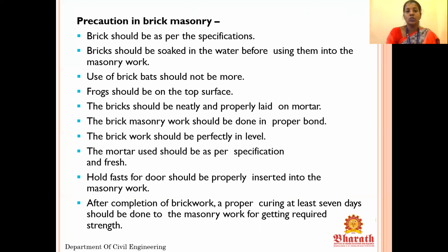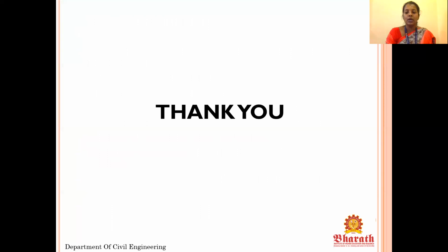while we are considering the bricks. So it should be as per specification. Brick bat should not be more. Frog should be only on the top surface. It should be neatly and properly laid on mortar. Brick masonry work should be done in proper bond. Brickwork should be perfect in level. So after completion of the masonry work, it should be properly cured for a minimum of 7 days and maximum of 14 days.